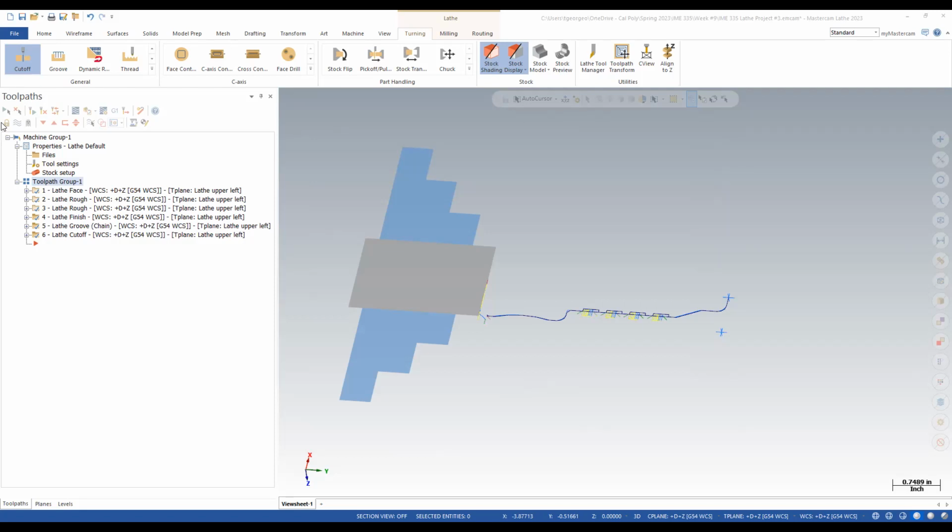Cool. Next tool change, I go down. This is the grooving. Lots of grooving, man. Look at that. There we go. UVW. Out. And then look at the PEC. Part off with PEC was easy, right? Just a bunch of X moves. That's all it's doing. Then UVW. I guarantee this will run. We're going to go run this.